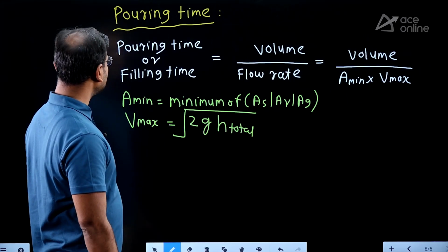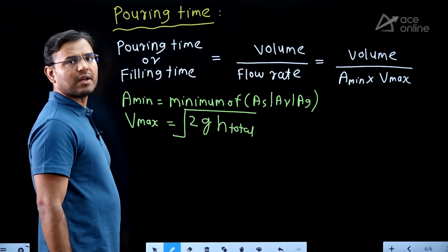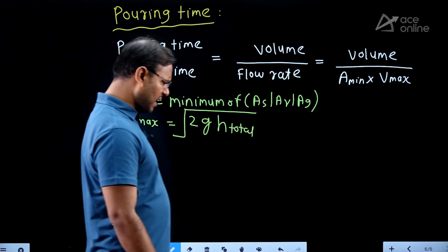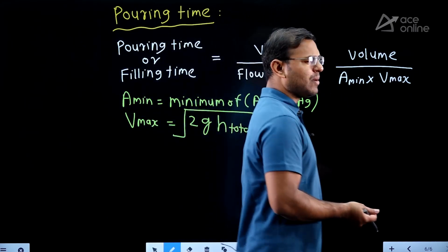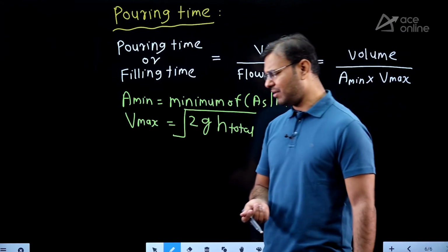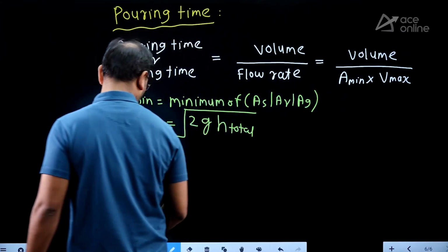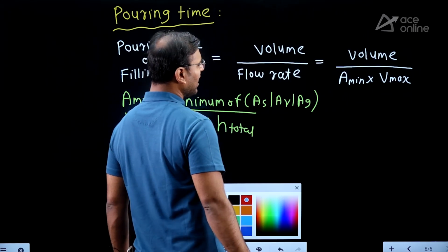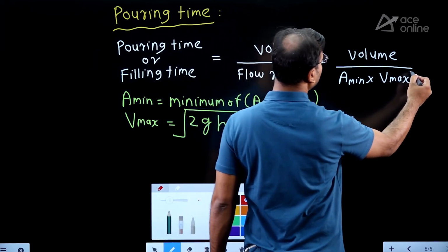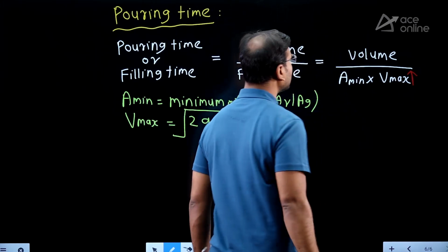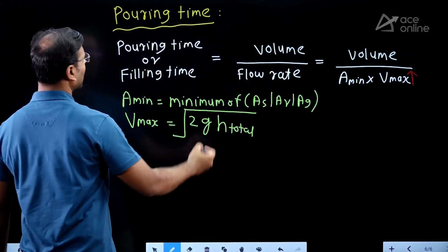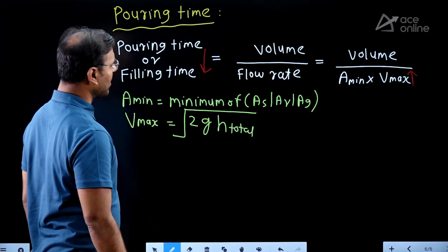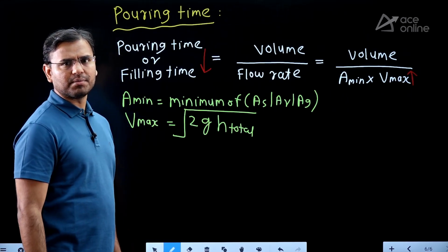Okay. Then guys, what pouring time do we require? Must the pouring time be high or low? Pouring time must be low, which means we pour the molten metal in the minimum time, and that is always better. Therefore the velocity of molten metal must be higher. If the velocity is high, then definitely the pouring time will be low.